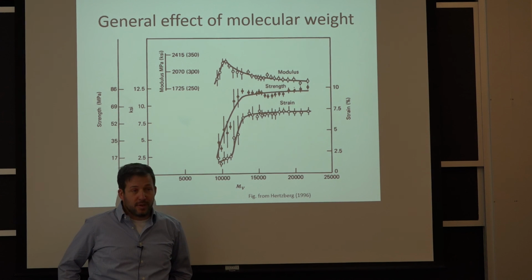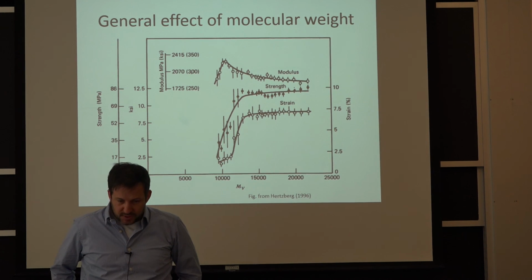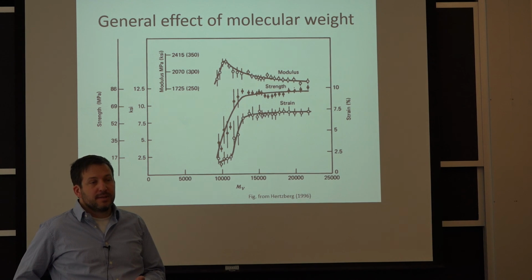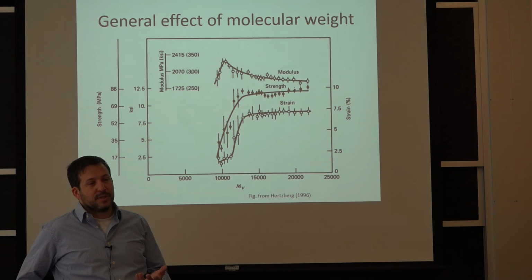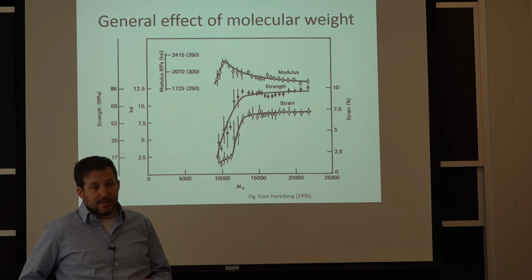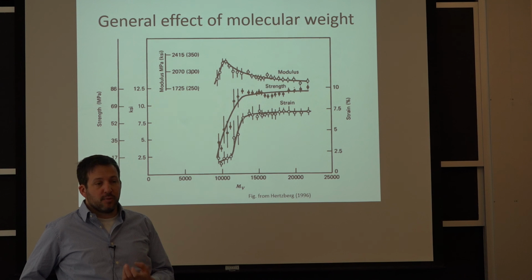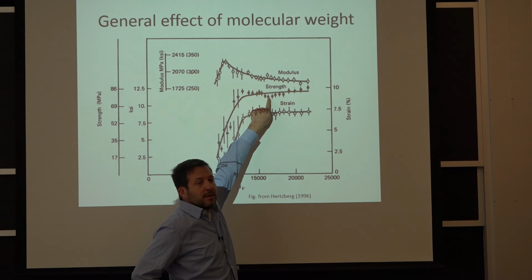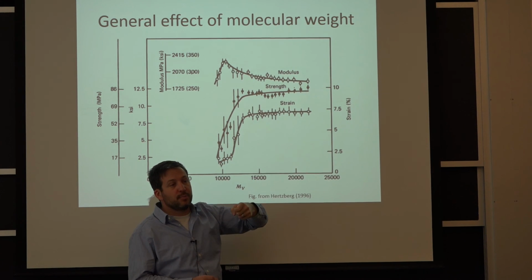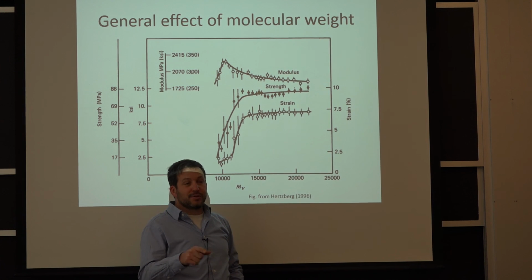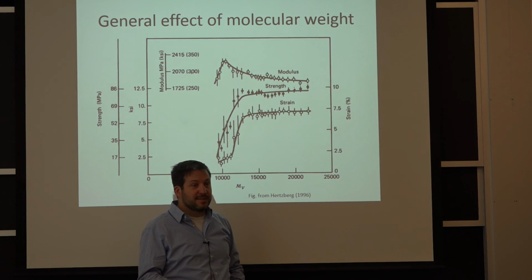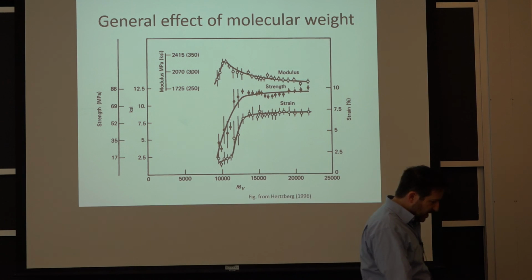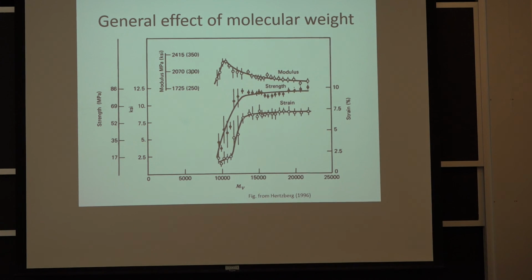We have to go back to the spherulite to explain it. So with the spherulite, if you have more molecular weight, it's harder to form the crystals. So you get typically less crystallinity for the same condition when you have more molecular weight. So less crystallinity means over here less strength. It's easier to deform it in the pull test. Does that mean it's weaker for service? No. Typically, it's the exact opposite. So essentially, the idea that you would compare plastics using the tensile test as an idea on how they're going to do in service doesn't quite work.